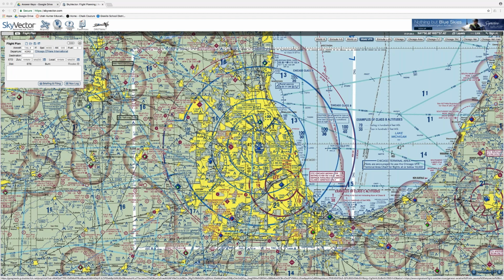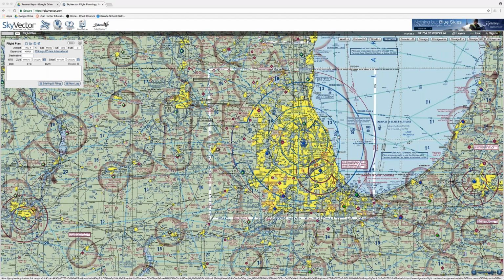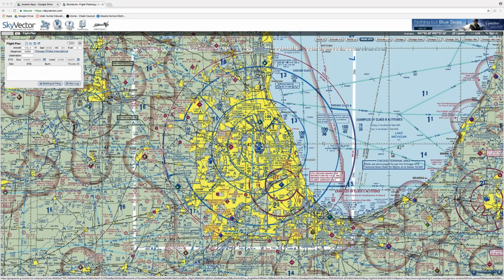these hard blue bordered airports with 3 rings that you can see here, these are Class B airspaces. Anything under that blue, and we're going to go really deep into this, but anything under this blue line would be considered a Class B airspace. And you can see that the Class B airspace typically goes 30 nautical miles around your busy airport, okay? You can see here that there's these. Can you guys see my mouse right now? Okay. Yeah. You can see these altitudes.